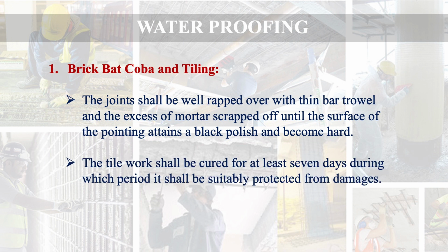The tile work shall be cured for at least 7 days, during which period it shall be suitably protected from any type of damage.